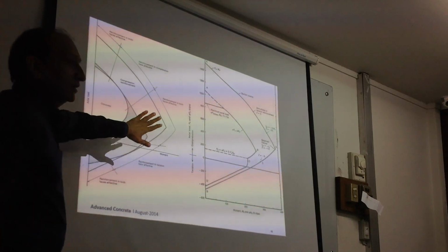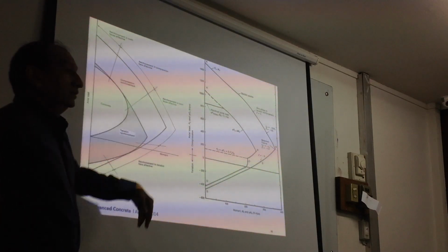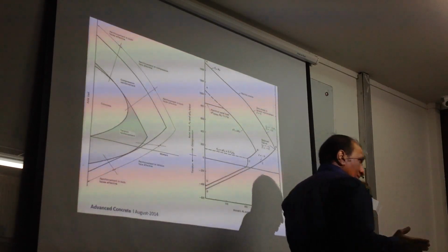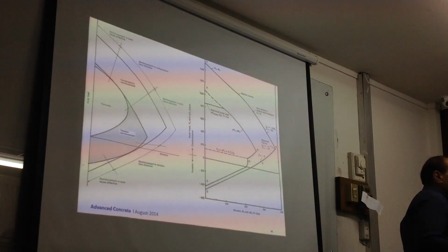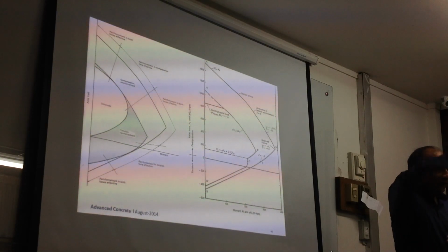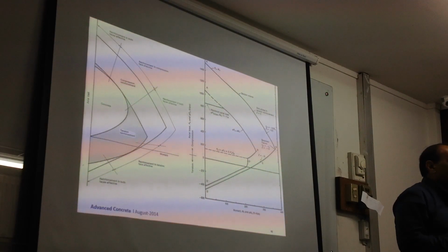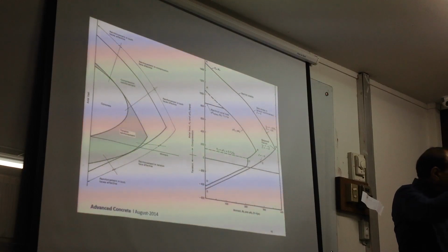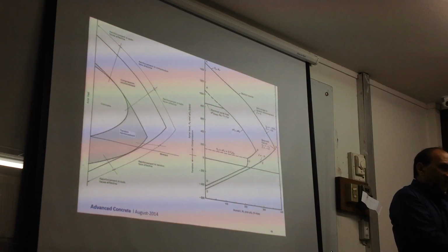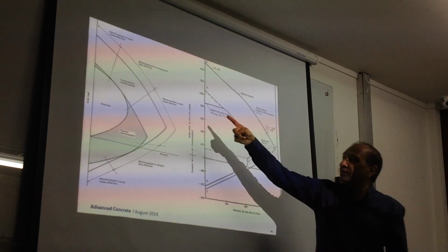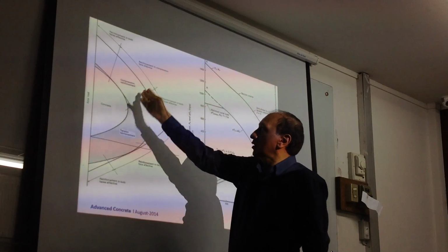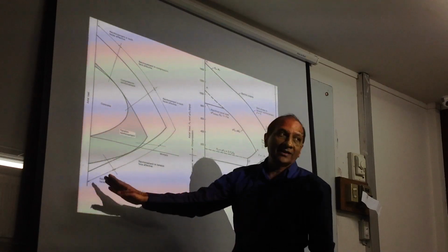So there are regions in the curve where the strain is such that the whole section will be in compression, no tension, right? Certain combinations of moment and load may not produce any tension because the load is high, moment is also there, but the compression will cancel the tension, so you will have net compression in the section. That is that range over here. So pure compression, a combination, and then pure tension, something like that.